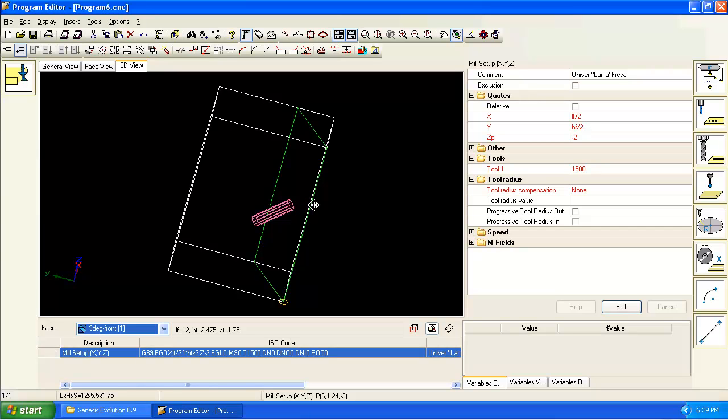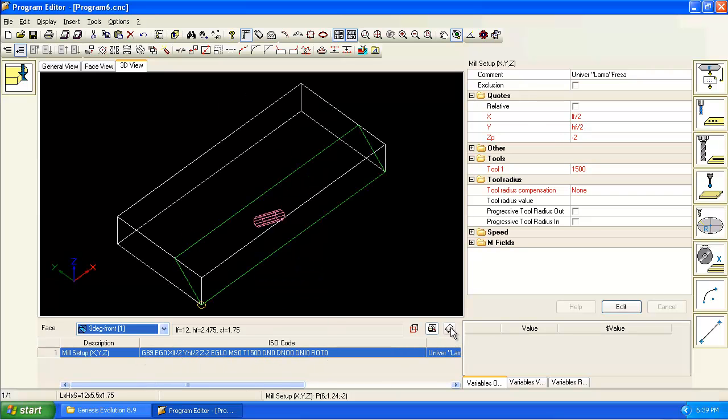So the machine would know to come in and approach, drill in, and come out on that 45-degree angle. It is up to us to set that aggregate to that angle, unless we had a 5-axis machine, that would actually tilt to that angle automatically. Or if we had the aggregate that can set its angle automatically at a setting station, then all that would happen automatically. If we have a manually set aggregate, then we have to set that angle ourselves, but the machine would know to move in and out along that 45-degree angle, and that same bit of code that we use to drill the hole on the edge of the door would also work on this face too.